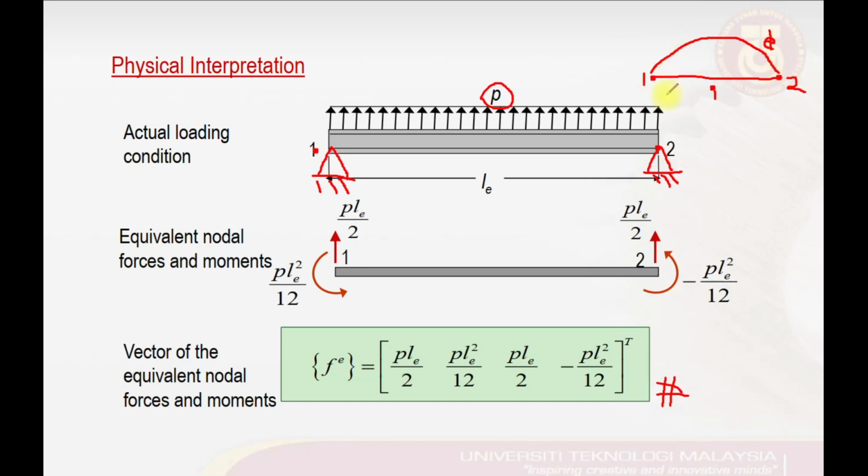So as we can see here, the deformed beam has the maximum deformation somewhere in the middle of the beam element, and the way it deformed here is something like there is a moment pushing the structure to form that shape. And of course here, since we have this distributed load that is pushing the structure in the upward direction,